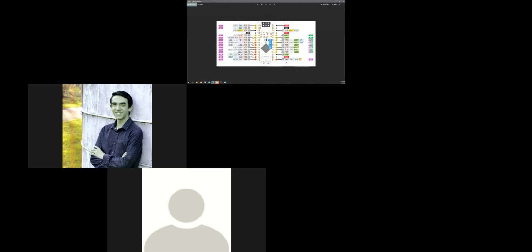There are a few pins that have specialized functions that, while they can be used for other functions, are mainly used for, for example, the LED matrix. Specifically, we want to use the SPI pins, that is pins 10, 11, 12, and 13. Those pins are more hardware oriented and allow you to send data and information quicker back and forth between different parts.